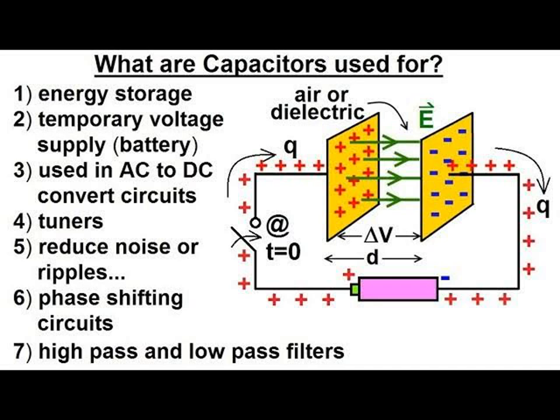So where do you find variable capacitors useful? Number one, they are very, very useful in setting resonance frequency in LC circuit, where inductive reactance happens to be equal to capacitive reactance. That's resonance. They are also useful in tuning radios, tuning control in radios and antennas. That's where you find variable capacitors very pertinent.